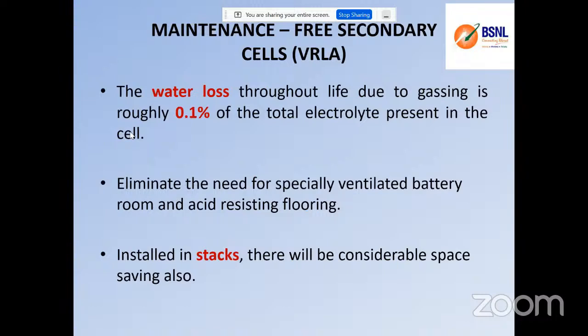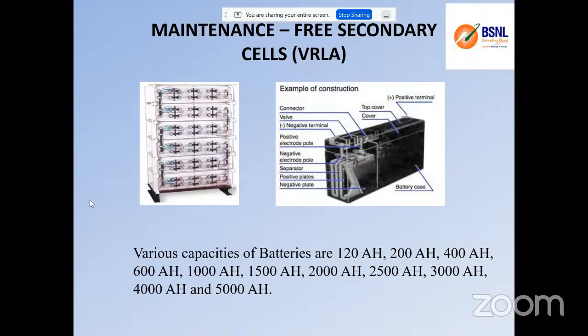That's it. And because of the spill proof, we can install it in stacks. Stacks means we can place one over the other. It will consume less space. Whereas you cannot do it with conventional batteries, because they need proper ventilation and proper maintenance. They have a chance of spillover, so acid and many issues are there. But here it is a fully closed container, so we can keep it stacked one above the other, so that we can have a minimum space. As the diagram shows, we can stack one over the another.